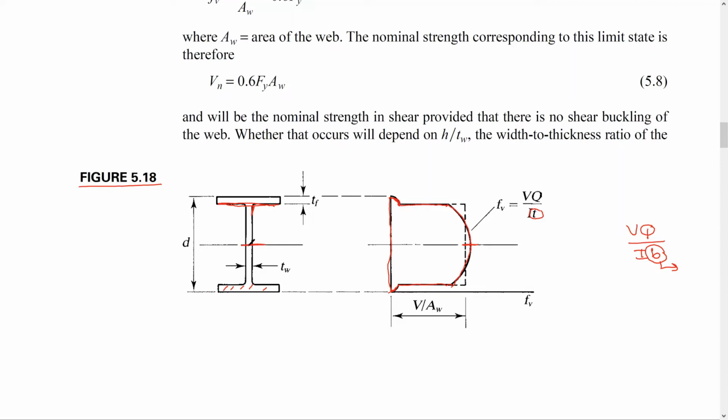So, and as you know, shear stress will be calculated based on this equation anywhere, okay? Because we do have a shear here that is, let's say, way bigger for the web. So that means the web will yield completely long before the flange begins to yield. Of course, here this is just an average.